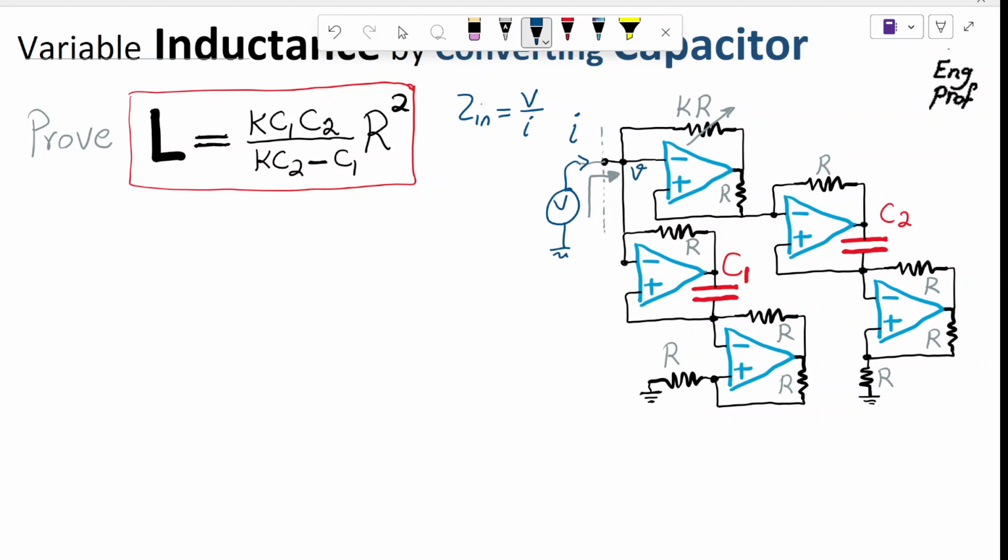Okay, so the voltage V is applied. Of course, V appears here. We assume that all the 5 op-amps are properly biased, with the positive and negative supply voltages connected. And we make the assumption that negative feedback as shown here is dominant compared to positive feedback for all op-amps, and therefore the circuit is stable in the linear region of operation, not saturated. Because of that, virtual short is valid, which means the voltage at the negative terminal of each op-amp is equal to the voltage at the positive input terminal for that op-amp.